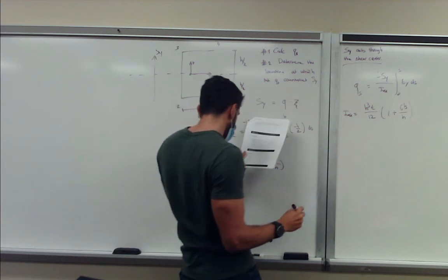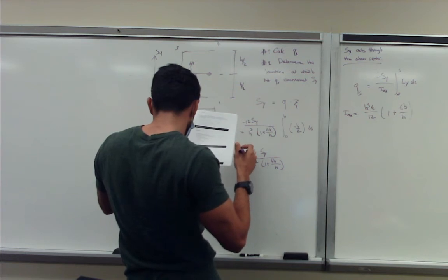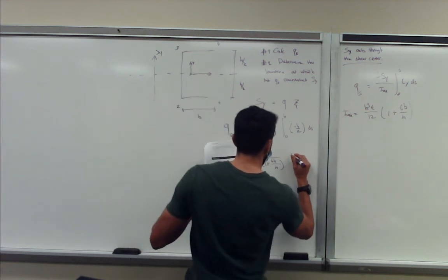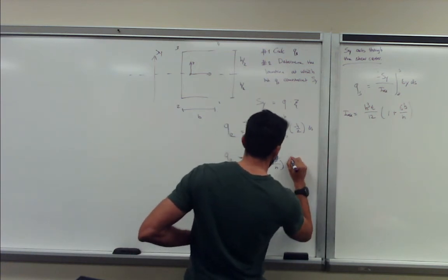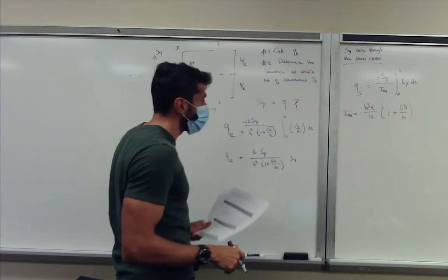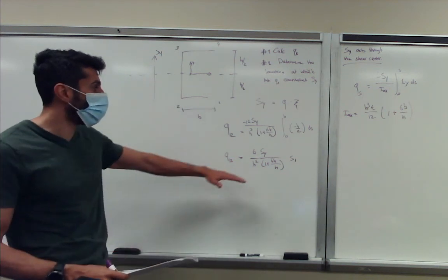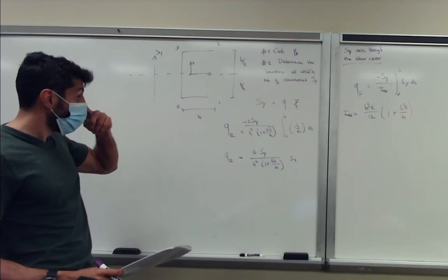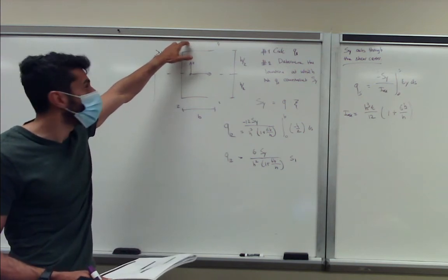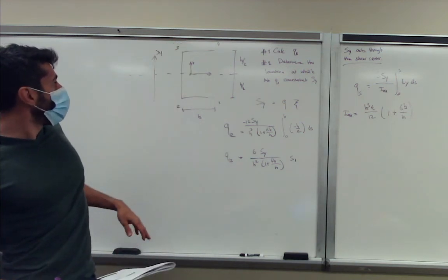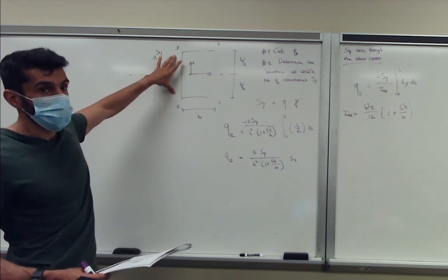And then we have the integral, let's call this S1. Because we take the integral, we just have S1 here, and S1 has to be evaluated from 0 to b. But this is the equation for the variation along 1, 2. So by definition, we know that Q12 is equal to Q34. And we don't need Q23 for this case, if we want to calculate the shear center.